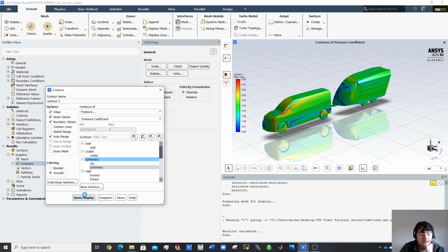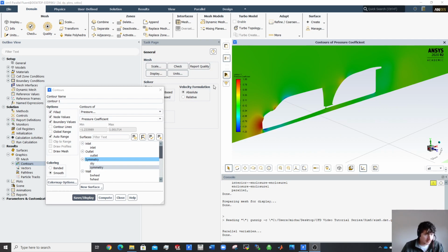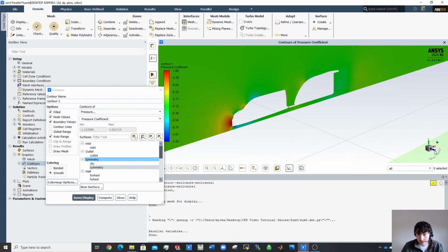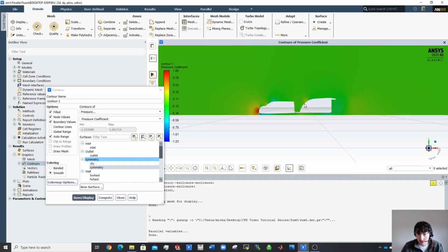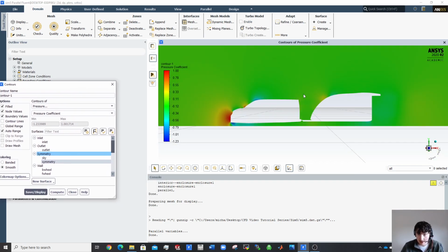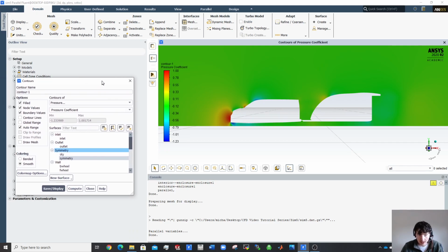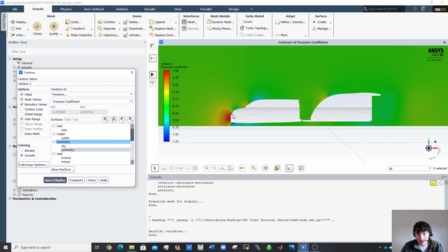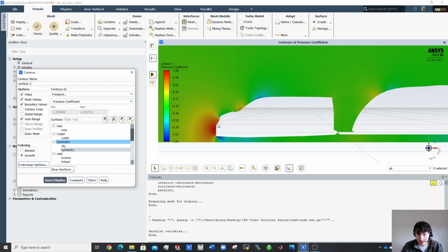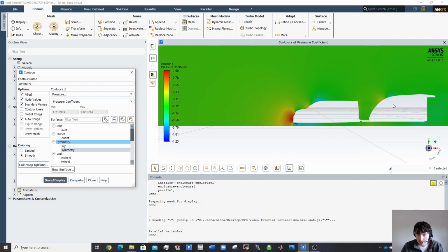Let's have a look at this. So hopefully this doesn't take too long. Same again, I'll just pause after every time I click on these. They're not taking long, but it just makes the video more efficient. Okie doke, that's loaded in there. It took a few seconds. If I look in from the side here, I can see the pressure coefficient, and that gives me a lot of information on where I have high pressure regions and where I have low pressure zones. As you can see there, CP of 1 at the stagnation, and it changes as it goes out.